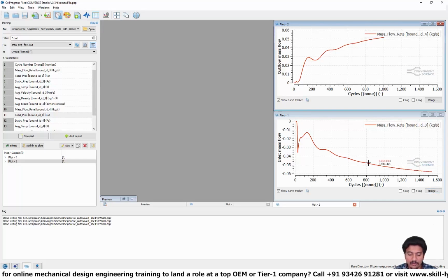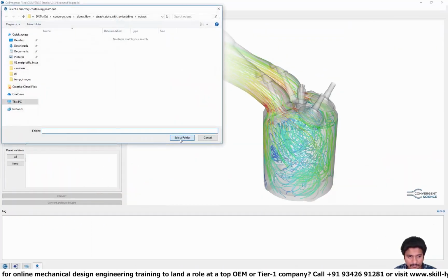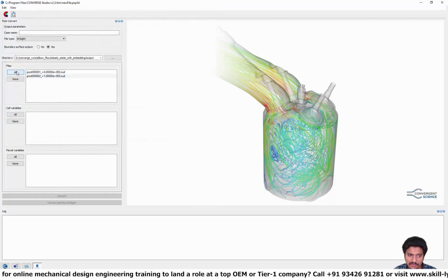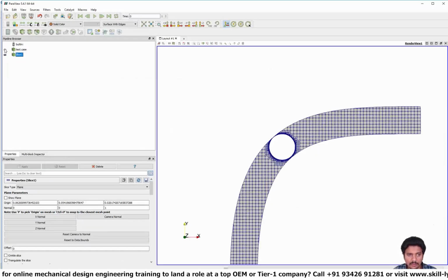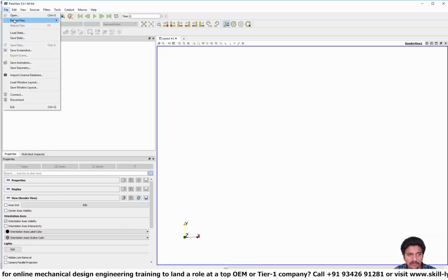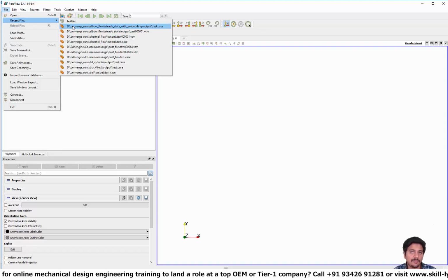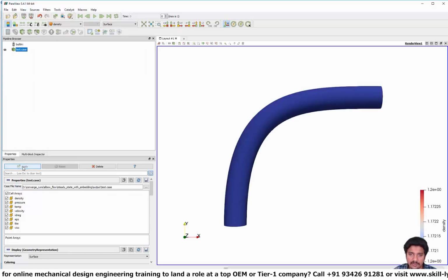So what I'm going to do is go back to 3D post-processing, and this time I have a couple of files. So let's just select all the files and then call it test, and then just convert it. All right, so the process is done. We can launch ParaView, delete our files and go to recent files, and then since the name of the case file is test, since it hasn't changed, I can just reload it. And when I click apply, you can see that there are two data points. There's time 0 and time number 1.